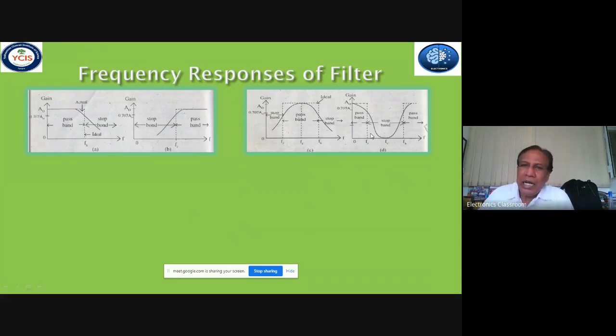So we call the band pass filter the acceptor circuit, and the band stop filter the rejector circuit. Why is the band pass filter called the acceptor circuit? Since at the resonant frequency, all signal will be transmitted without any attenuation. That means it can accept all the data, so it is known as an acceptor circuit, and the gain is maximum and current is maximum.